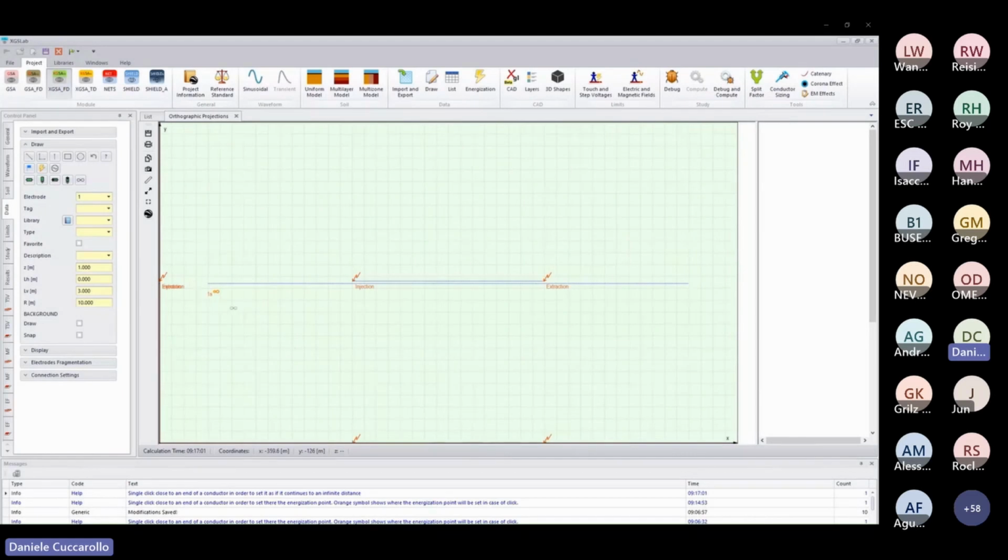And the most important detail of this new feature is that if you change the soil model or the diameter of the pipeline in this case, or the material of the pipeline, or the conductor that you are using for the pipeline, the value of the ZT that is used to simulate the continuity to infinite is automatically updated. So this is the most important news about this feature. The continuity to infinite becomes a property of the conductor. You can set it also on this.